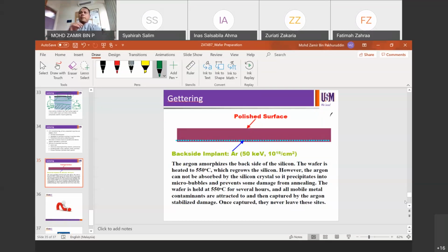This actually depends on where you have the impurities, or the impurities that you need to remove. If you have impurities after the diffusion process, that means the phosphorus gathering during the diffusion is not so efficient. So you then need to revisit the gathering efficiency after the phosphorus diffusion process.